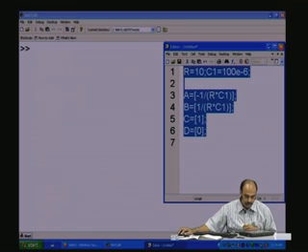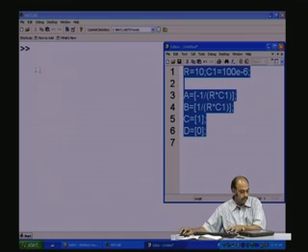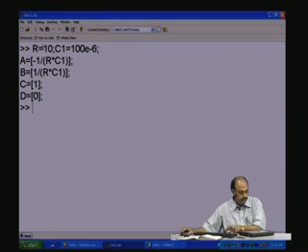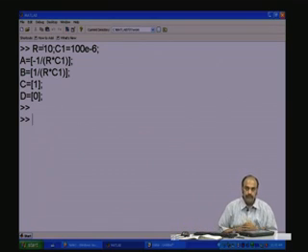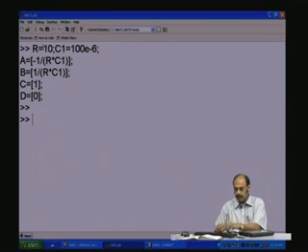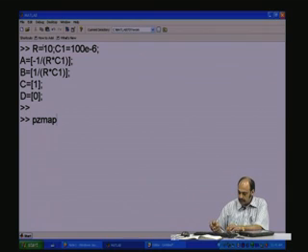We take the model, paste it here, and then you have the model in MATLAB. There is one function called pzmap, or pole zero map. This is a function, and to that function we input the model A, B, C, D, and let me give grid.